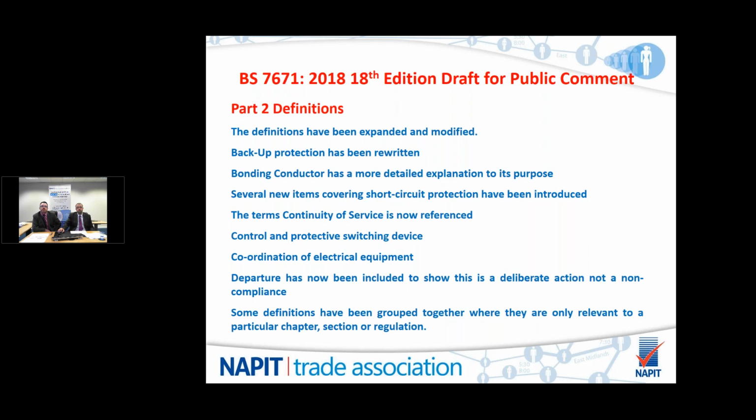Departure. This is an important reference because previously departures have been added to as a defect, but a departure is a deliberate action by the designer of an installation to include equipment that is not included within the requirements of the regulations, but must be seen to be carried out to no less a standard of safety than would apply to BS 7671.